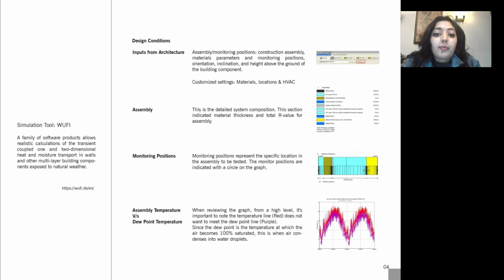And lastly, we have inputs from HVAC and process that we need for indoor climatic conditions. These can be defined as per standards of the location of the project. So if you're using the ASHRAE or the European standards, that can be defined. And these basically include the temperature and humidity and air change rates. HVAC requirements of the room need to be confirmed by the HVAC department. This is like one collaboration work with inputs from every department.